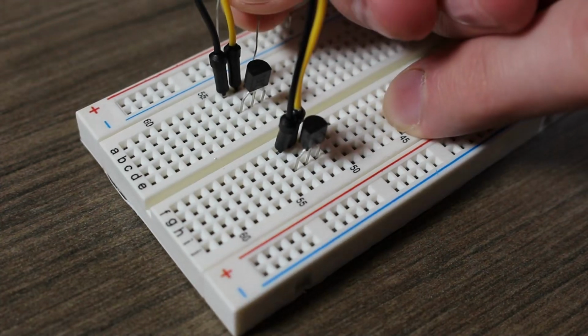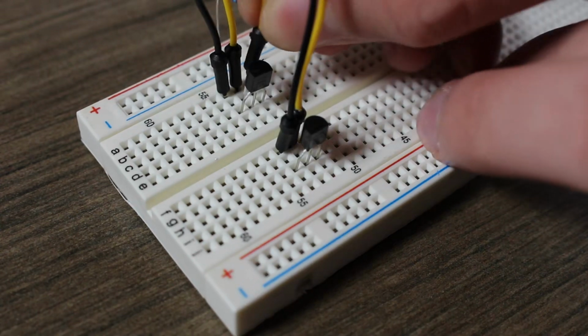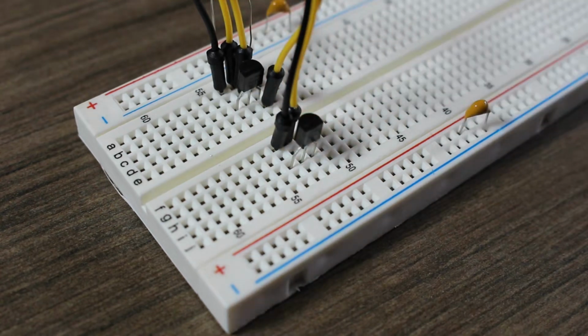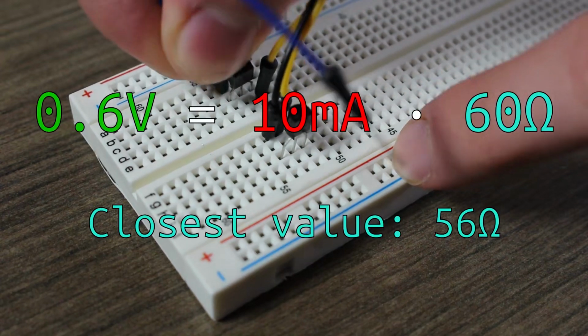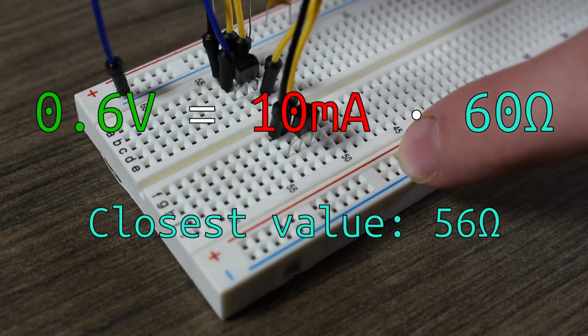R1 and R2 should both be somewhat large in order to reduce power losses. So I chose R1 to be 10K and R2 to be 1K. Now, R sense is where we get to choose the current limit. Now remember, the current is determined by Ohm's law, and V is stuck at 0.6 volts because of the diode.